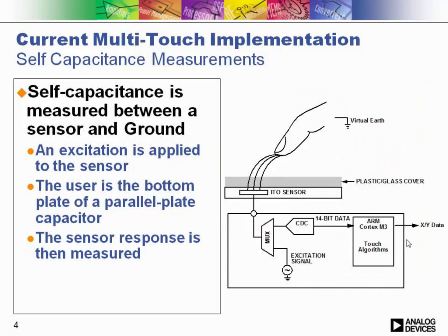There are different flavors of these sensors, and one of the differences is what capacitance you measure. In this case, for this work, it was the capacitance to ground, what we call the self-capacitance. So we excite the sensor, we measure capacitance continuously, and detect where it changes when you put your finger down on the sensor.